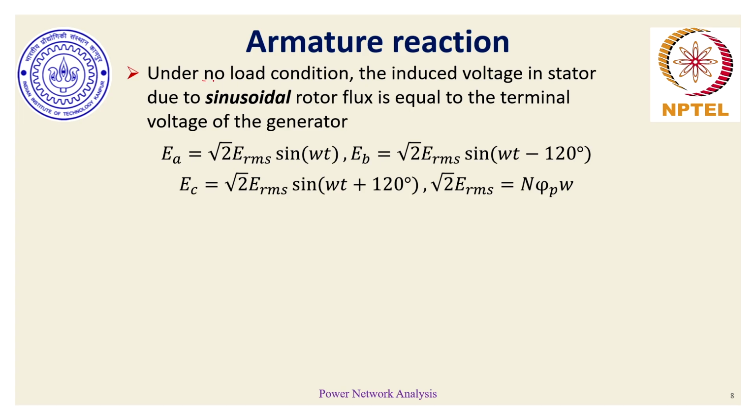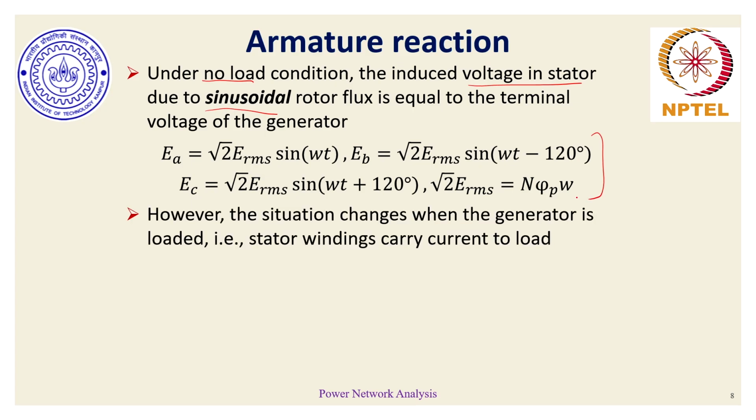Under no load conditions, the induced voltage in the stator, due to sinusoidal rotor flux, is a balanced positive sequence voltage. But things change dramatically when stator windings carry current. That means if there is some electrical load connected to the stator of the synchronous generator, the induced EMF would try to supply the load, and this supply can only happen when current tends to flow. So when current flows, stator windings will also carry current.